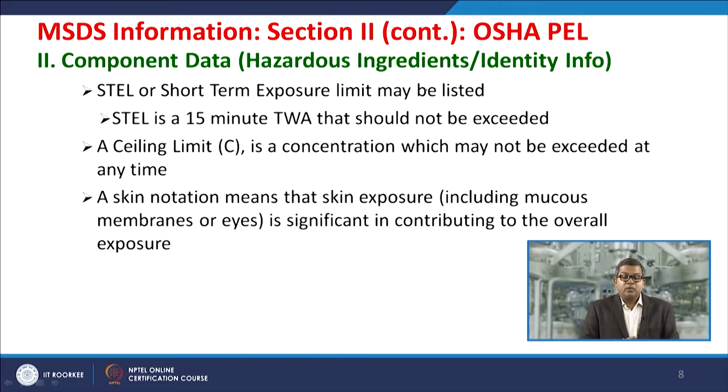The short term exposure limit should also be listed, so that instantaneously the workers should not be overexposed. The ceiling limit, usually a concentration which may not be exceeded at any time, should also be there if applicable. A skin notation usually means that skin exposure, including the mucous membrane or eyes, is significant in contributing to overall exposure.